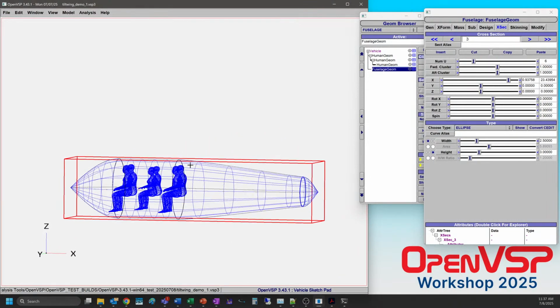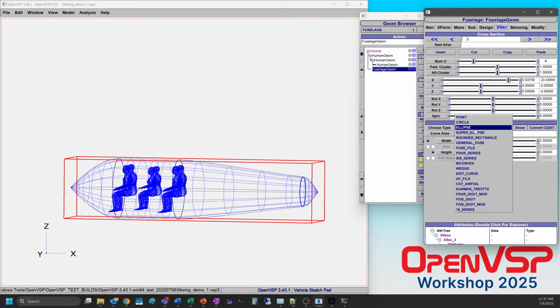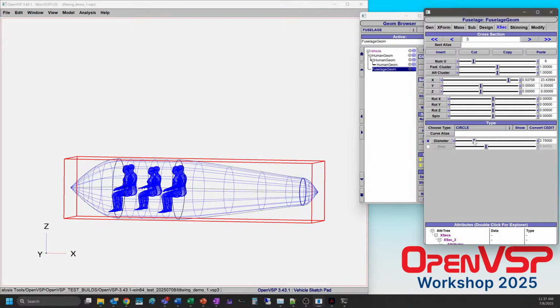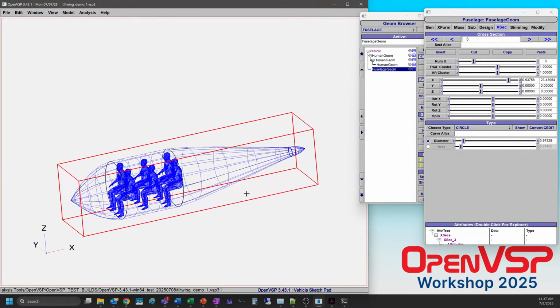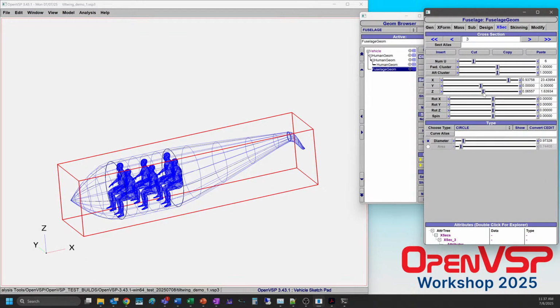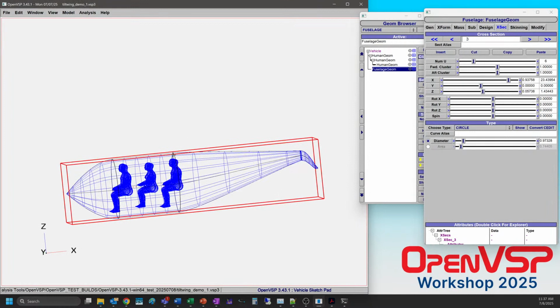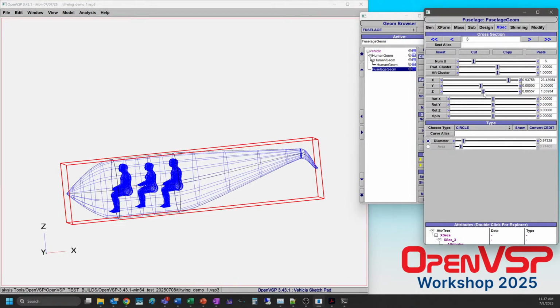While we're at it, let's go ahead and make this a circle. We're going to change the diameter so that it's a bit more like a tail, maybe something like 1 foot or so. We don't have to be really fancy with it. Then what we're going to do now is shift this up. We want to have something that's a bit more of a flat shape here on top. Now don't worry about that weird little ghost tail at the back. We're going to fix that too.